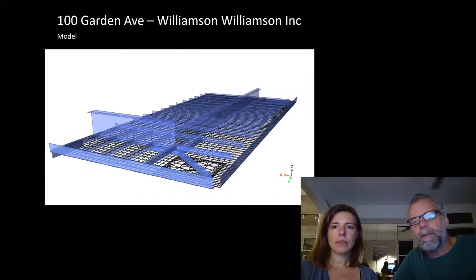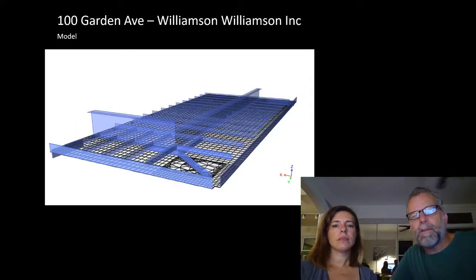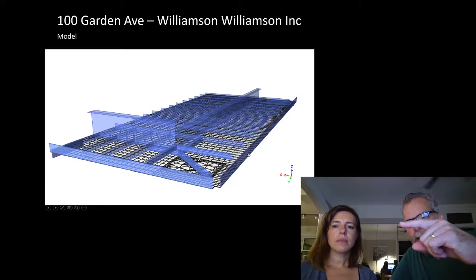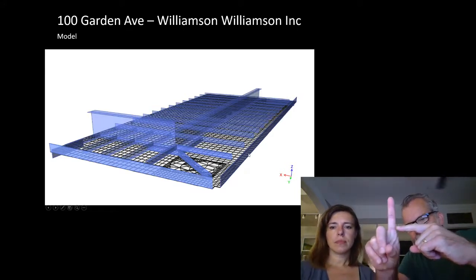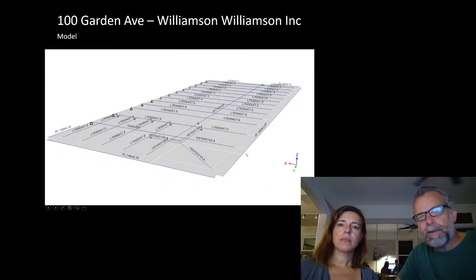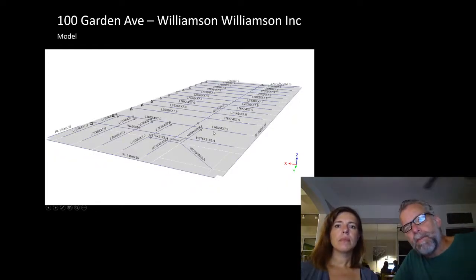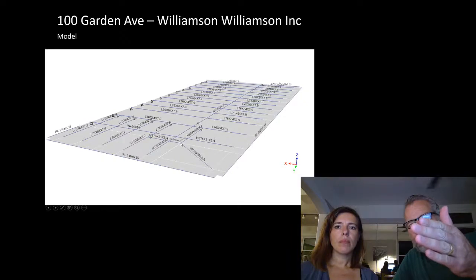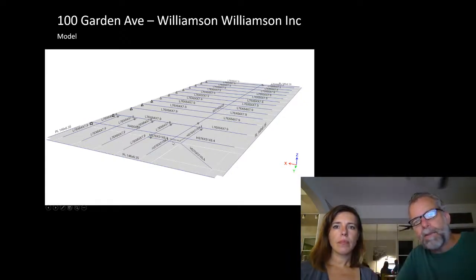I think this is really clever, Shannon, and you can see it in this one as well. The corner detail. Shannon talked about the way you can add vectors. You can add rotation vectors the same way you would add translation vectors. And so the moment at the back of the diagonal beam coming out splits and goes in 2 orthogonal directions, which avoided having to do a very complicated moment connection through 2 elements that were crossing.